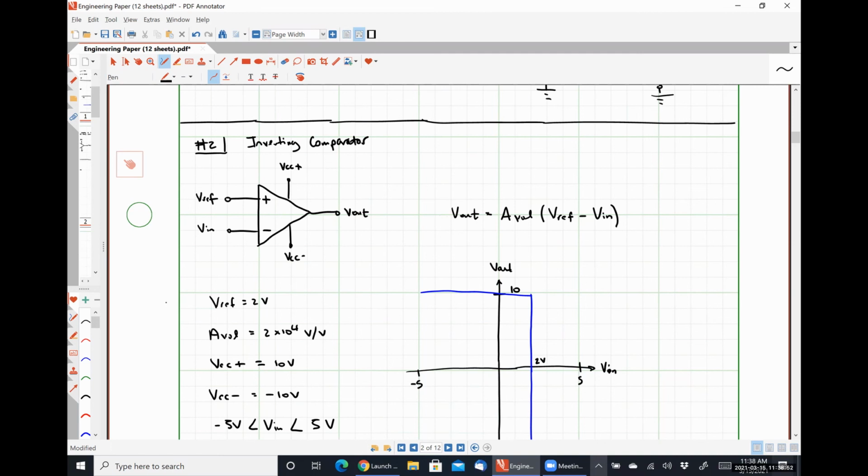Open loop circuits are literally these two options. We either have a non-inverting comparator or an inverting comparator. We can apply our reference voltage either directly with a DC voltage source or using a voltage divider where our resistors are in the kilo ohm range to make sure that not too much current flows and starts messing things up. Any questions? All right, so that's all I've got for today.